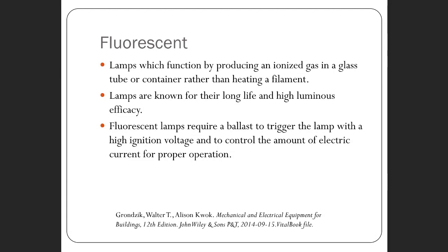The difference of a fluorescent is that it needs a transformer or a ballast to regulate the voltage that is passed between the filaments in that fluorescent lamp. So fluorescent typically has a tube and a ballast in some form or another.